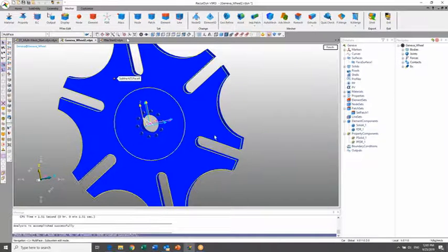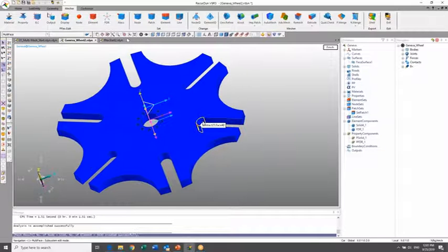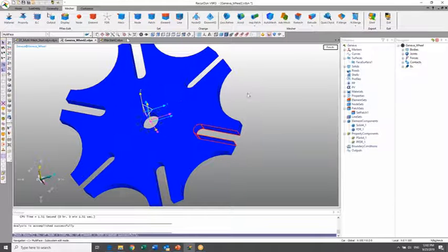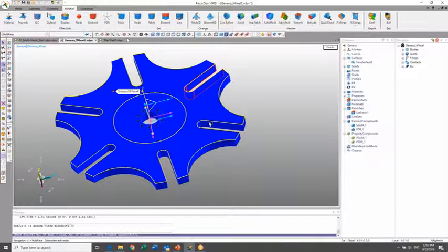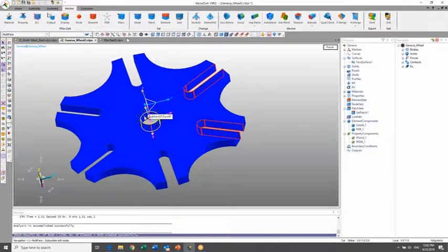Now there are all of these different surfaces here, but if I click on one, it'll actually add everything that's within a certain tolerance, and that's kind of what I'm looking for at the moment. If you click on something else, it will take away what you've already done, so you hold down Control, and there you go. We don't need to get everything. We'll just leave it at those 3 so that you can see how the local remesh compares.